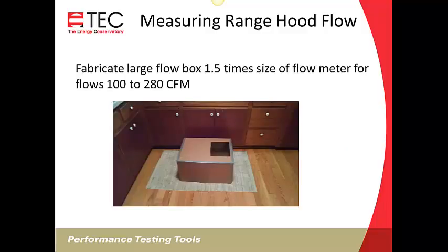So this is an example of that flow box that's 1.5 times the flow meter. It'll work for measuring flows from 100 to 280 CFM. Remember, you want that pressure in the box between 1 and 8 in order to get accurate measurements. At least 1 pascal, so we're getting enough resolution on our reading, and not more than 8 pascals, or you're going to start restricting the flow through the box. So we fabricated that just out of lightweight cardboard again.